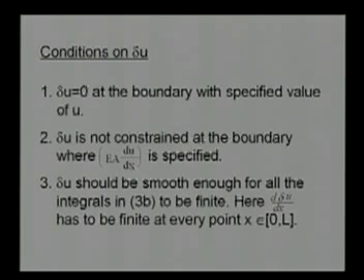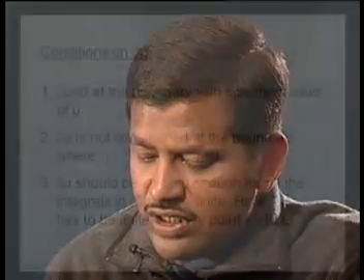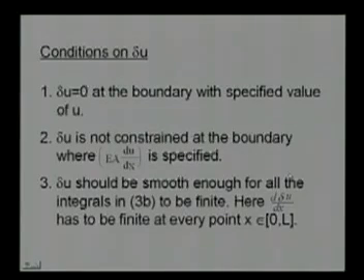Third, as we have shown in the weak formulation or the principle of virtual work, all we need is that the derivative of delta u should be defined in the domain. So when the derivative is defined, then the integrals that we have in the variational or the virtual work formulation or the weak formulation are all finite.